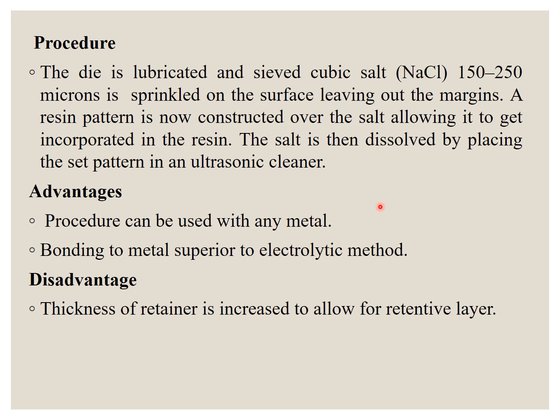So a die is lubricated, sieved cubic salt is sprinkled on the surface, leaving out the margins, and then a resin pattern is built over the salt, allowing it to get incorporated in the resin. The salt is then dissolved by placing the set pattern in an ultrasonic cleaner.